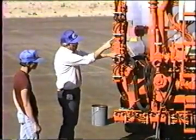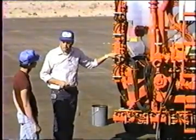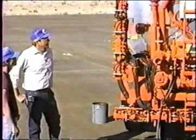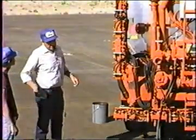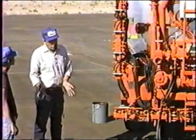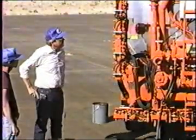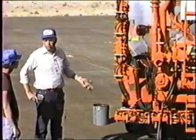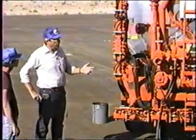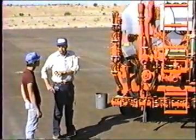Obviously, if we wanted to put down a quart, or 1/4 of a gallon, to the square yard, if we're asking for a specific quantity for every square yard, the spray bar has to put down the same quantity all the way across the width of it. And that's the reason for all this equalizing system, so that we put down exactly the same spread rate all the way across the spray bar.